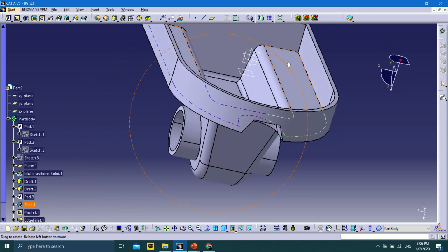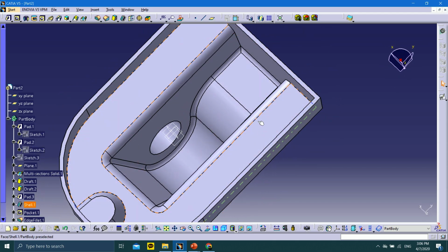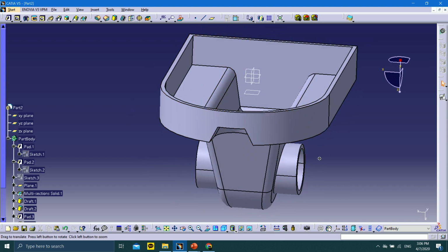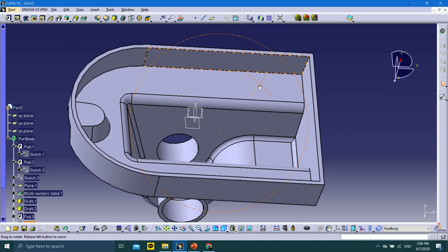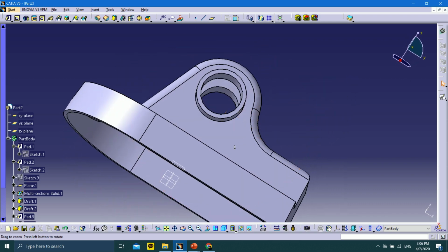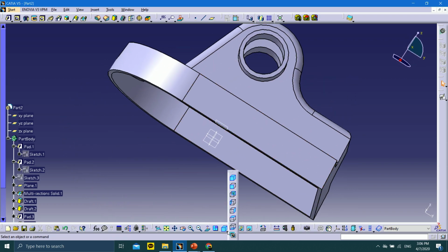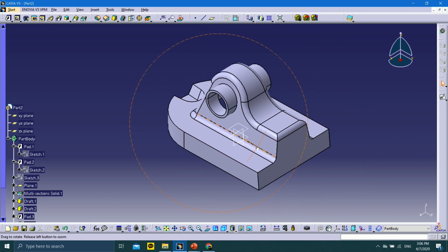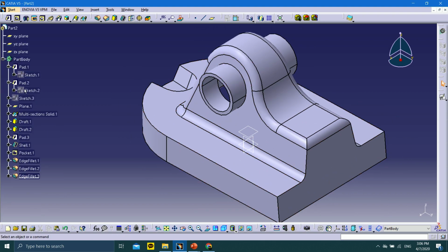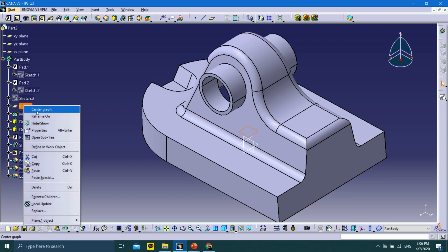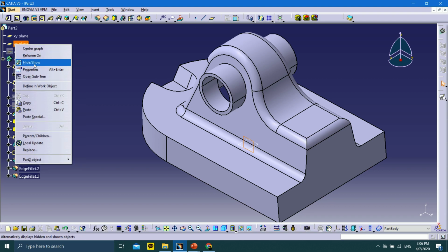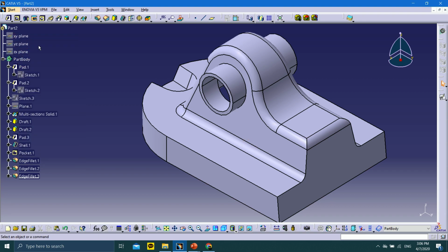So this is your final drawing for bracket shell 2, the second bracket shell. Okay, the last job is you can hide this plane, which is maybe annoying, or you can hide this one also, the XYZ plane.